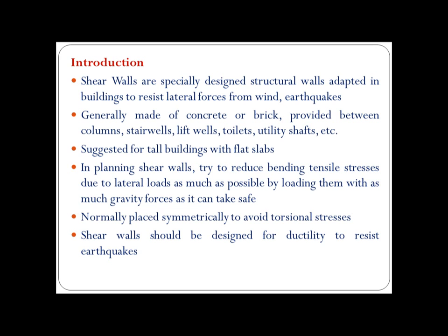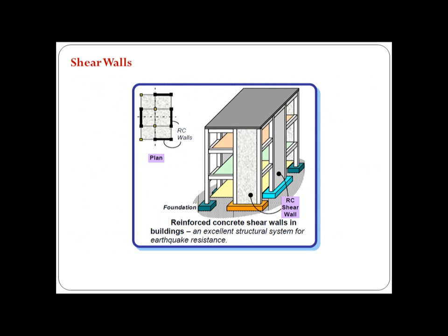We need to ensure that we place the shear walls symmetrically so that we avoid torsional stresses. Shear walls which have been used for resisting earthquake forces have to be designed for ductility. This is a picture of a shear wall. We can see that walls have been placed symmetrically in both the orthogonal axes in plan.